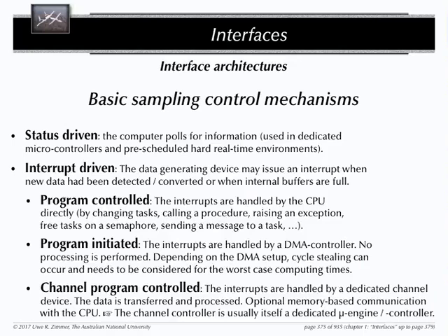Everything else is a more complex operation, is somehow interrupt driven, but the target of your interrupt is not necessarily your CPU. You can set up your device so that it gives you an interrupt by the end of an operation, and whether this interrupt is handled by your CPU or some other device is still open. Okay? What other devices could we have here? It could be handled by a DMA controller, for example.